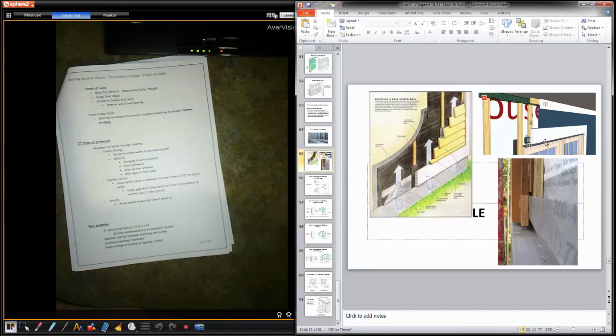You can see the same thing over top of a window screen. So strapping's all vertical. Never horizontal strapping. If I put a horizontal strapping on top of a window, the water gets behind the siding, and that strapping is now going to hold the water. That's the common thing people want to do when they have a window. You look at the apprentices, they did it. They put strapping around the entire window first, where you should have verticals only, so that when the water hits, it follows the house wrap, gets onto the drip cap, and then comes out of the building. When people aren't trained properly, that's what ends up happening.